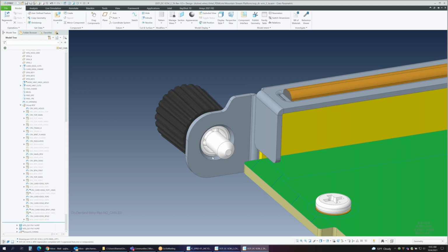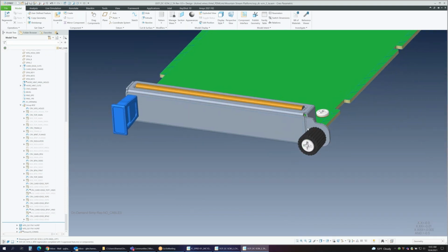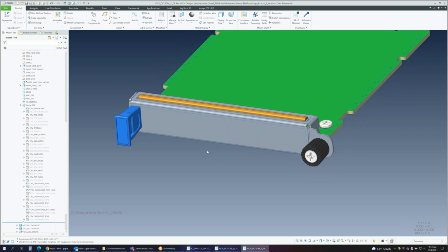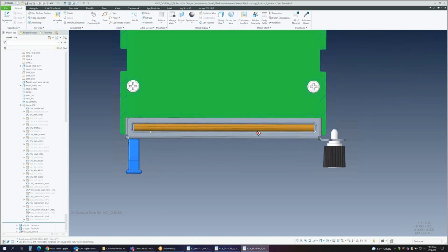This thumb screw is what we call a flare-in, meaning it is swaged to the back side of the sheet metal so that it has real retention in case someone pulled the screw instead of a handle, right? So we're not too concerned about this being used as a handle when it really shouldn't be. Other things: I modified the bracket to make sure that in general it matches the OCP NIC bracket aside from the width.